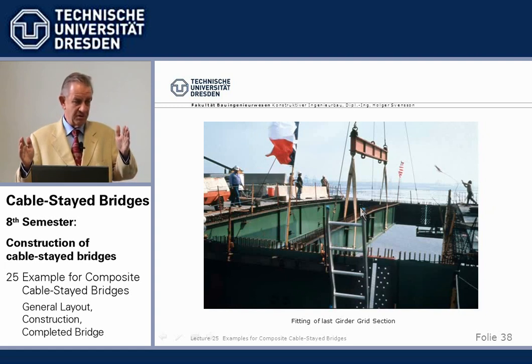The 2 beam halves were moved back at the towers. You remember we had there these corbels, some joints, put a jack in there, pushed outside. So the whole half beam moved to the outside.